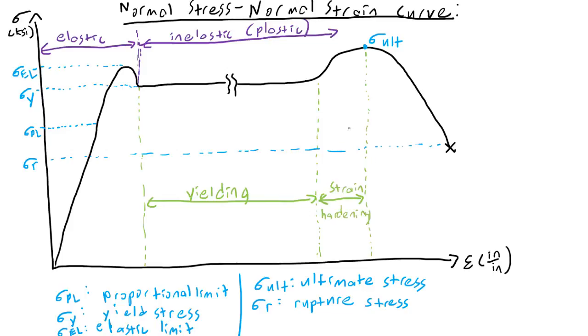You gain a little bit extra stress from the stress that's already there. On very large deformations, very large strains, you can get a little bit extra stress, and that's what allows you to get that peak at the ultimate stress. This peak here is higher than this generally. This really is the ultimate stress of the material.